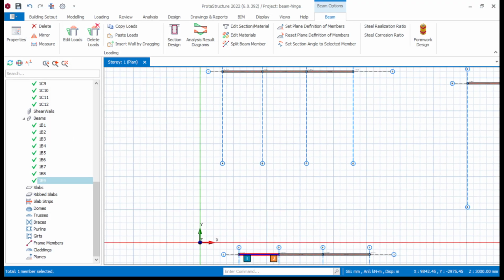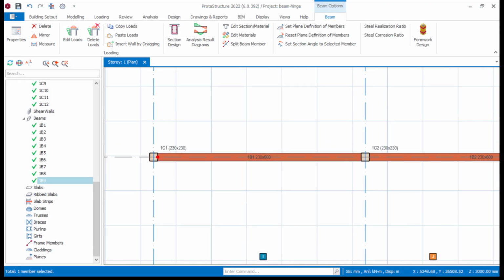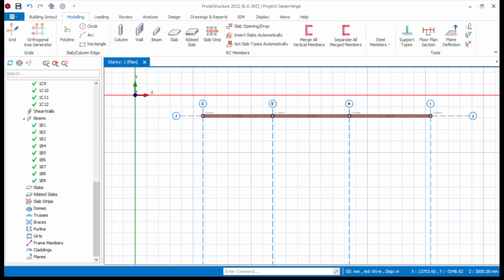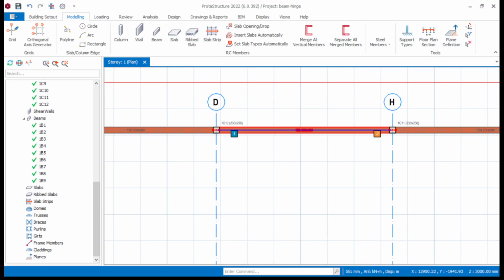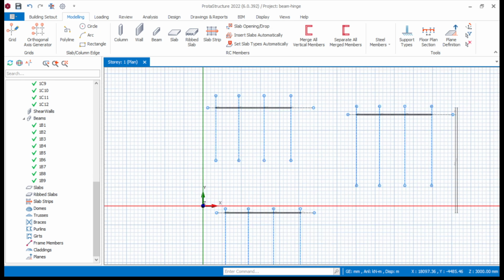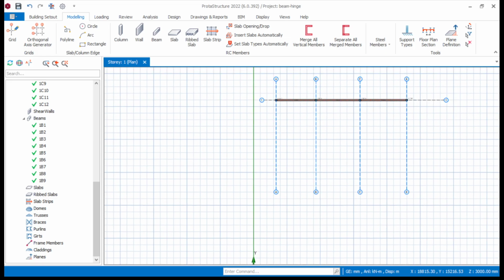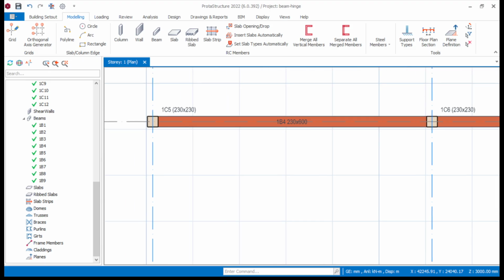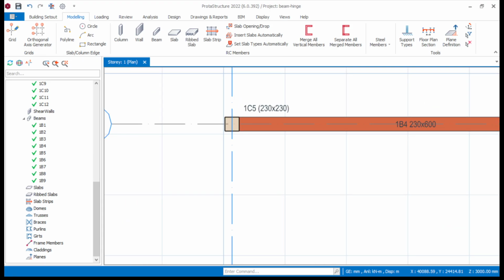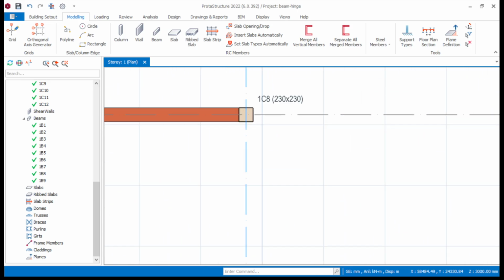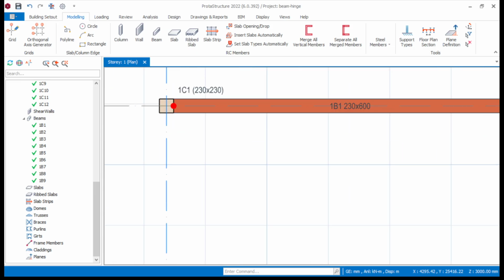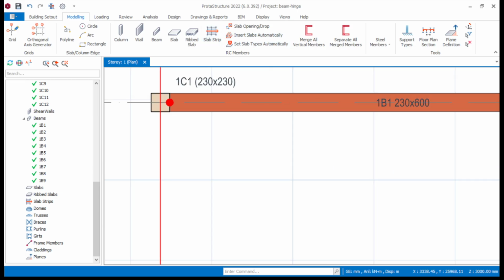Like I said before, in this one the two supports at the end were hinged. In this one, none was hinged. And in this one, everything was hinged, just to explain the concept as to why we hinge beams. I've already shown you the analysis result. This one that is not hinged is going to induce a moment on the support here. This one is also going to induce a moment on the support here, right? But for this one that is hinged, the hinge is saying that you do not want a moment to be transferred to that point. That's why it's being hinged.